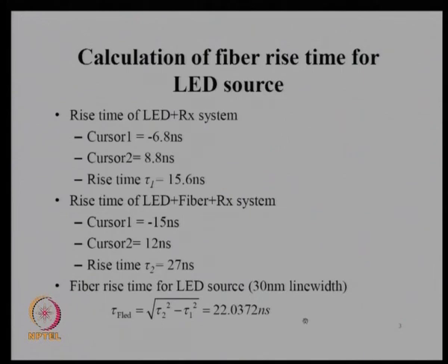Now similarly, we will calculate the fiber rise time for LED source. The rise time for LED plus receiver system from our readings comes out to be 15.6 nanoseconds, and the rise time of the LED plus fiber plus receiver system comes out to be 27 nanoseconds. So as in the previous case, we will subtract the effect of rise time of LED plus receiver system from the total rise time to get the fiber rise time for LED source, and the fiber rise time for LED source comes out to be 22.037 nanoseconds.